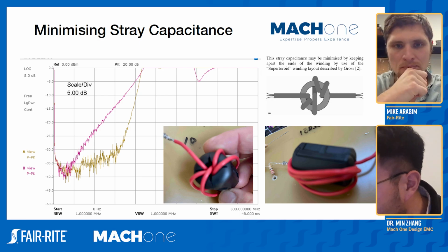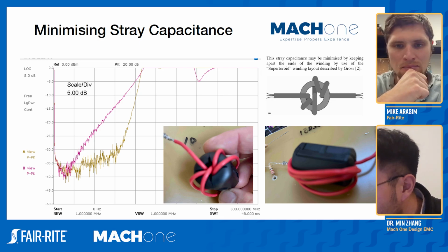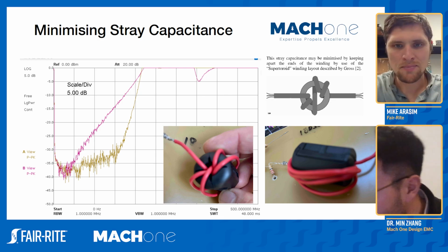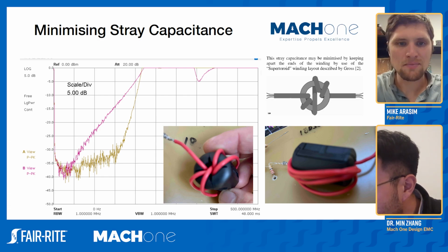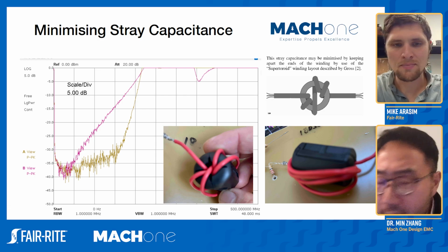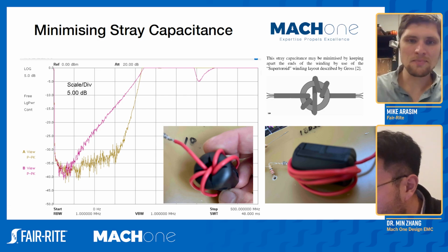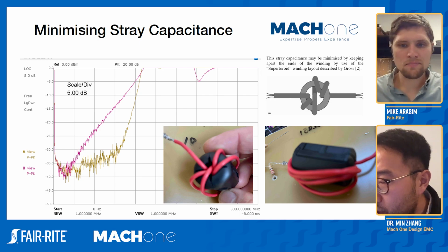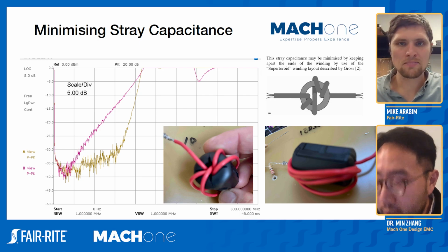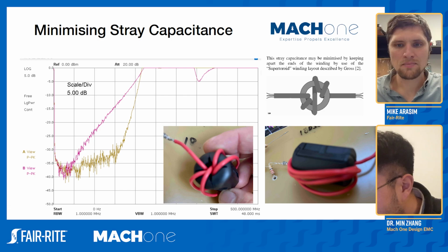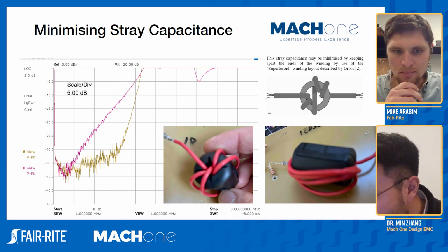So in this case, I have to mention that it is a 5-turn configuration, so quite a lot. Therefore, you start to introduce the turn-to-turn capacitance. And these capacitors are quite small, but at higher frequency, hundreds of megahertz, now they started to make a difference. Hence, we see this peaky kind of performance.